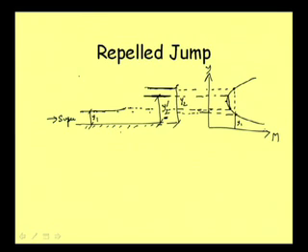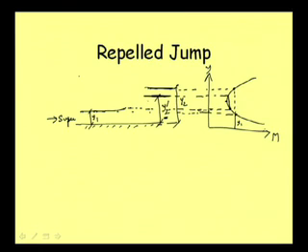If it is horizontal, of course, it is at infinity, but if it is a mild slope, still the normal depth will be higher than the critical depth. So the normal depth will be somewhere here, and this zone is zone 3. And we got that in zone 3 the gradually varied flow profiles are rising profiles: if it is over a horizontal floor, it will be H3, if it is over a mild slope, this will be M3.